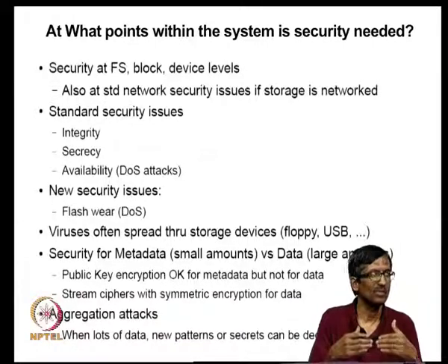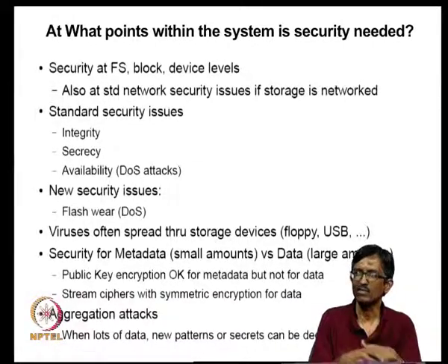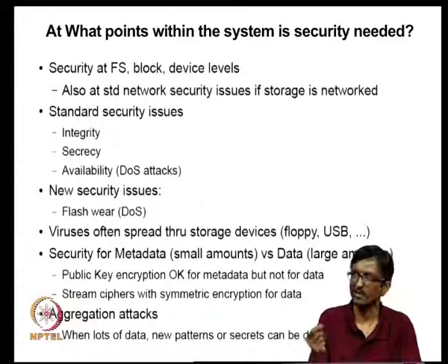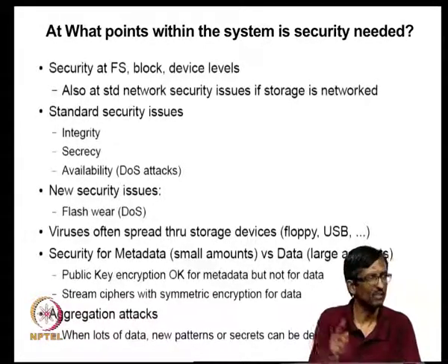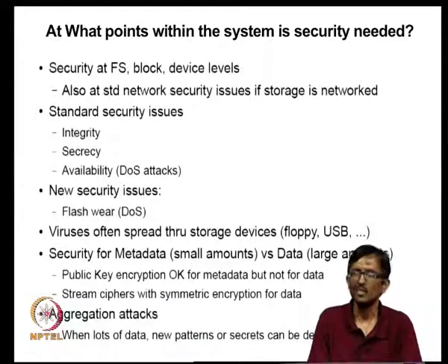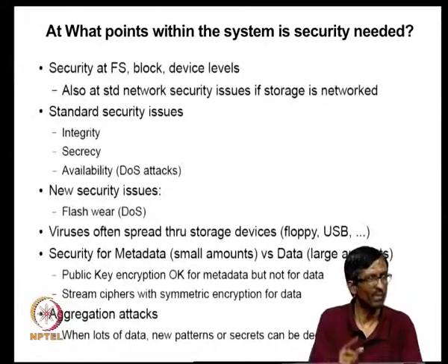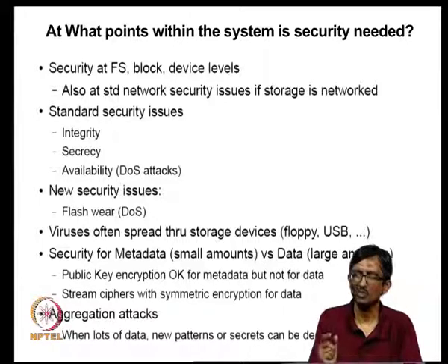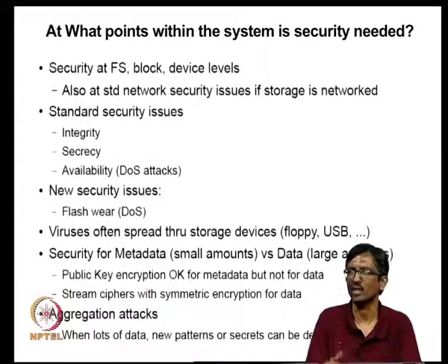The idea is to keep writing in such a way, just like you do in core memory, looping across a single word and only touching one particular area. Here also, in spite of wear leveling, you try to make so many writes that your spare capacity is completely gone, and people finally have to write off the device. Somebody has to take it offline, copy it, etc. Essentially, it's a DOS attack. So that also is possible.